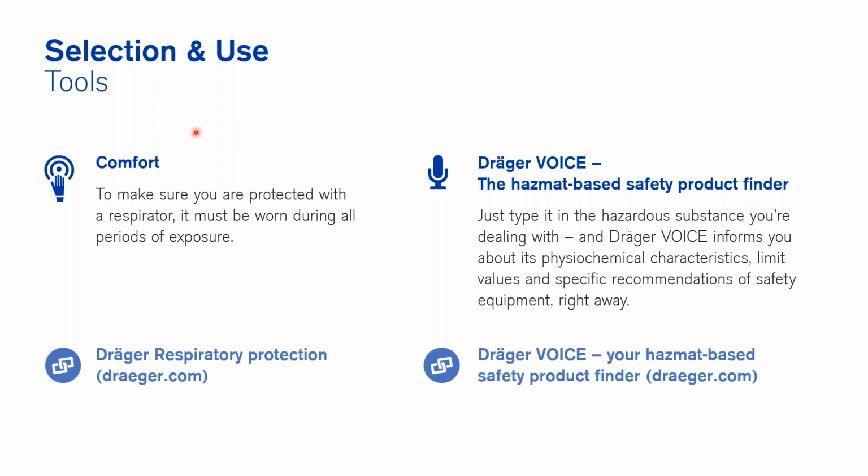You also need to take note of skin comfort. Skin comfort will be affected by the smoothness and softness of the inner material of the FFP when in contact with the skin, especially when we look at wearing an FFP for a long period of time, like 8 hours. So a soft inner face seal and even a sweat-absorbent nose foam will provide greater comfort, while rough or hard materials, coupled with high temperature inside the respirator, can cause an itchy and unpleasant situation.